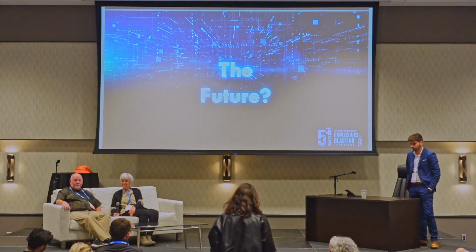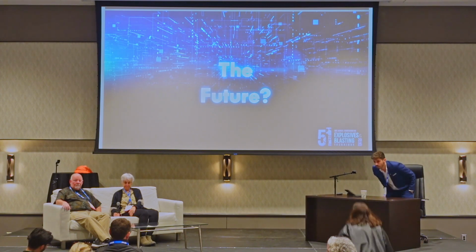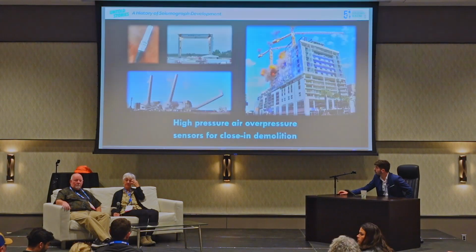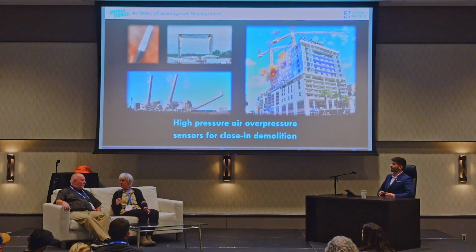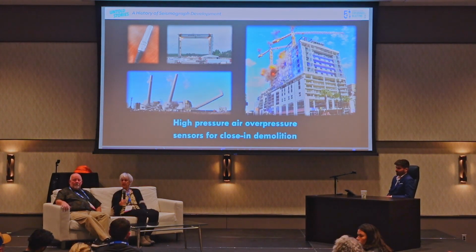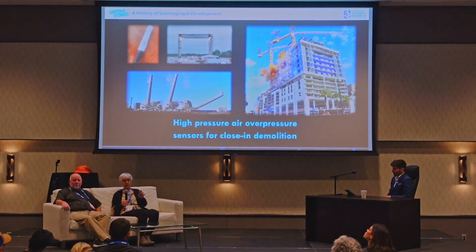Getting a reading of 10 psi from some of those demolition projects, how does that correlate to a decibel level? Oh my goodness, what's 10 psi to this? Well, it's like 180, 184, something like that. We haven't broken glass with that. I'm going to tell you right now, you know me, I don't believe these limits for damage. But we built windows at ATF and hit them at about 180, 190, and we have not gotten a broken window.